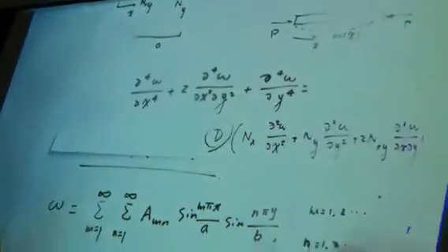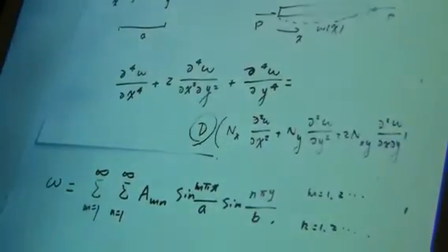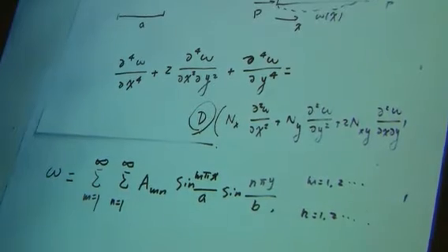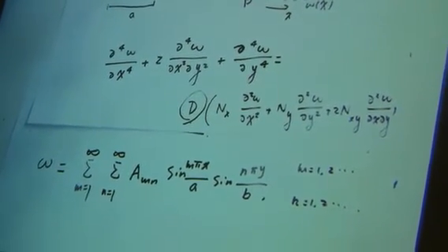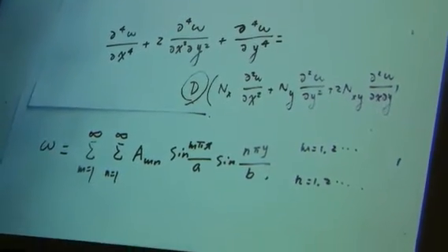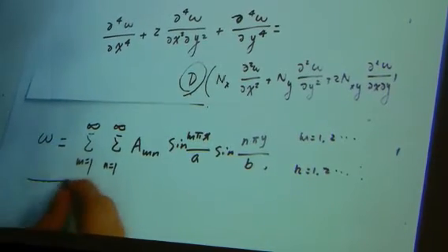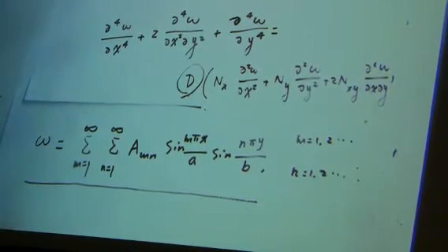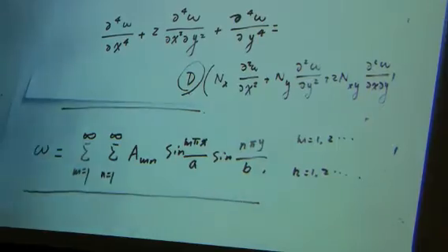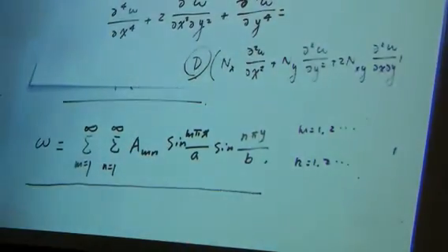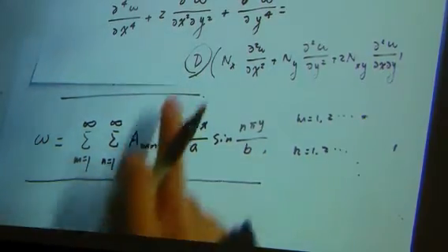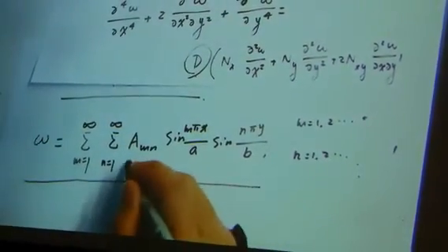That gives me some information about what the deformed shape should be, because the deformed shape should at least satisfy the boundary condition. So a deformed shape like this function will satisfy the boundary condition at least. And then you can substitute this deformed shape into this equation and solve for the unknown.